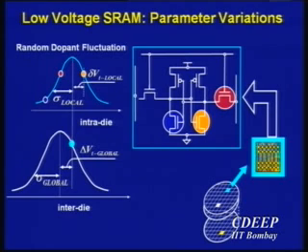fluctuations. If you look at logic, I usually have stages of logic, right? 3, 4, 5 stages. And if they're random variations, they will cancel out if the number of stages is large enough. If you have 2 stages, of course, that's bad. But if you have a number of stages, they might cancel out. So in the logic case, I didn't really consider that in any detail, though it does affect, but it's not really a major problem. But in memories, your NMOS transistors can potentially have different variations.